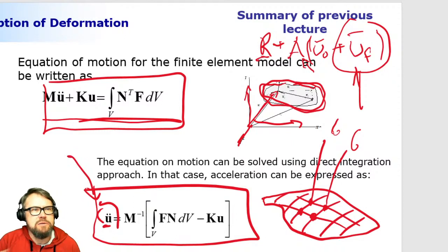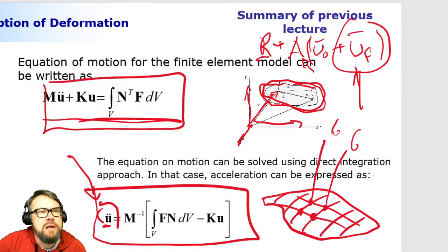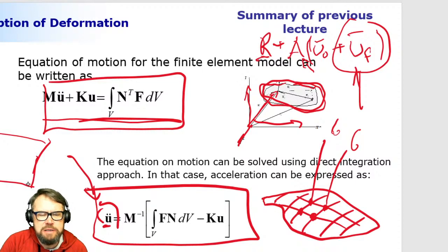And now there is a question. I need to take a look at the comment. Okay, why 6 degrees of freedom? Well, the 6 degrees of freedom depends on the element type. But typically when you're looking at the plate element as a single element, there is a nodal displacement with respect to the element reference coordinate system. So it's a displacement vector r, which in a spatial case has components along x, y, and z. And typically there are rotations around these axes as well.